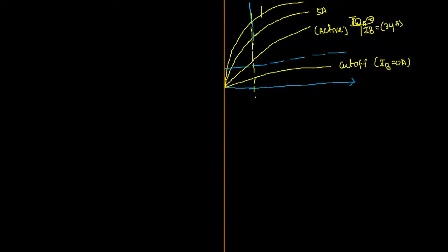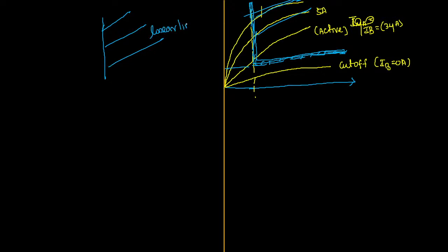So the area that I am covering here. So here this is only area, right? So let me mark it. This is called the safe operating area or linear operating zone. Your device will be in the linear zone. If you observe, almost this device will be a linear line, a ramp line, that is called a linear line. So it keeps on linearly increasing with respect to what? X-axis. So that is called active region.